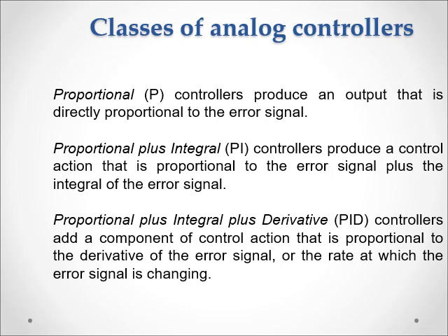to be unstable, and your system will become very much vibratory. A little bit of change in the error signal, maybe due to the noise, will cause, if you give a very high kp value or the p value, a very unstable system. But if you keep a low kp value, then a small error cannot be overcome due to the limitations. So that is the problem. You will always have a steady state error if your proportional constant value is low. But if you give a high proportional constant value, the problem is it will cause unnecessary vibration to the system.